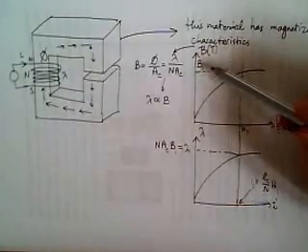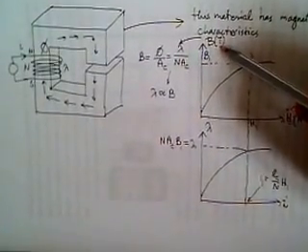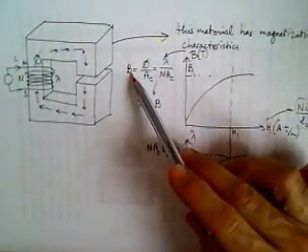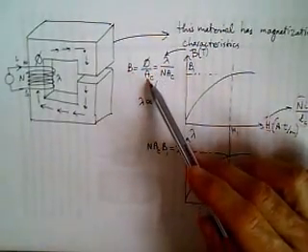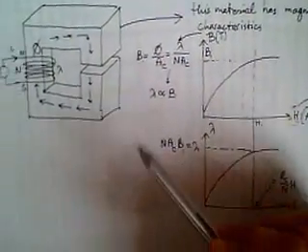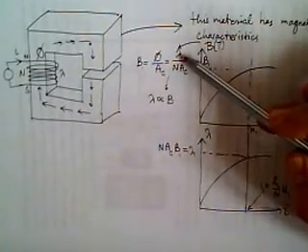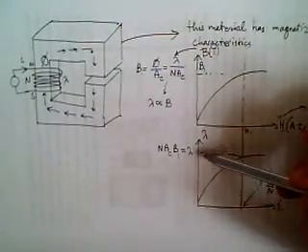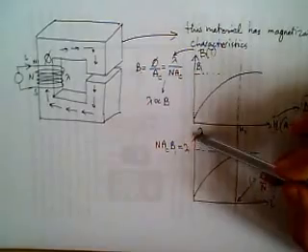Similarly, the vertical axis is magnetic flux density, and its unit is Tesla. Magnetic flux density equals the magnetic flux over cross-sectional area. This area is again a geometrical constant, or instead of flux we may write flux linkage over N. So we may construct an equivalent curve with another axis unit. Okay, this is flux linkage.